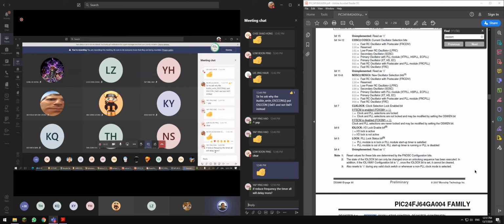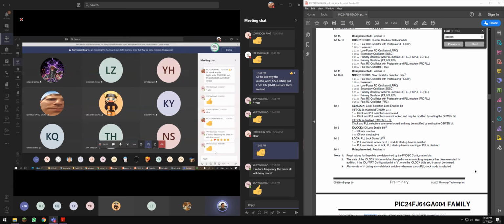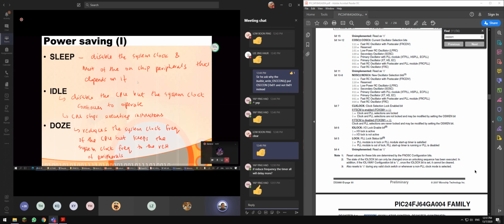All right, in a sleep mode, in this doze mode. Okay, is it all right, Ying Hao? Because the timer calculation is according to the real FCY. Let's say you're using 8 megahertz, means you are using 4 megahertz. Okay, thank you, Ying Hao, for this question. Very good. Okay, let's move on.